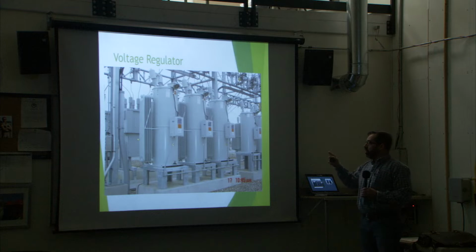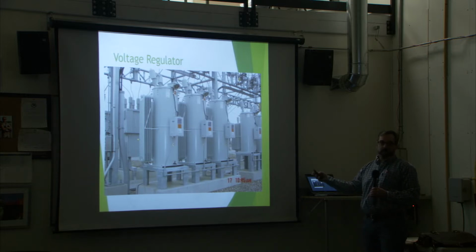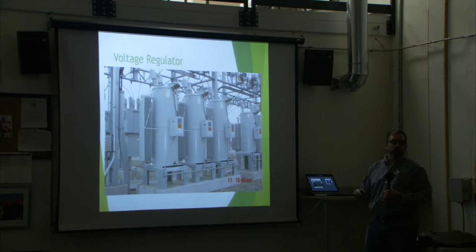Usually our distribution bays have a set of voltage regulators installed in series with the distribution circuit. Again, this is to regulate our voltages in our system, and it's also used for matching circuits at different substations when we have to do some switching.